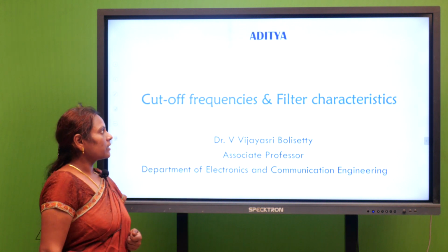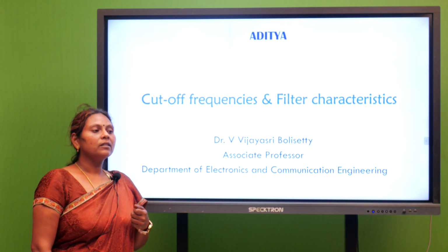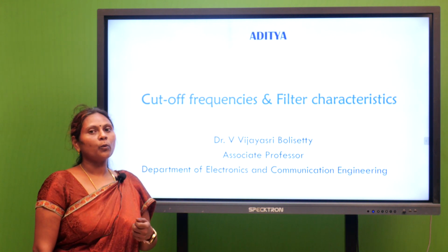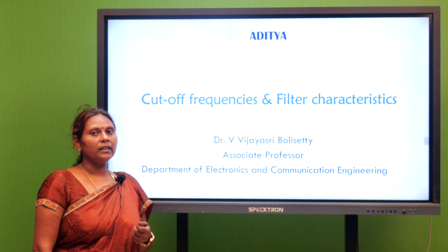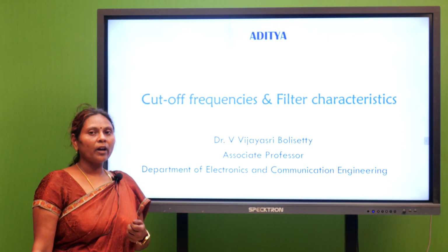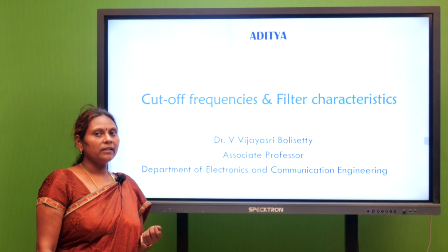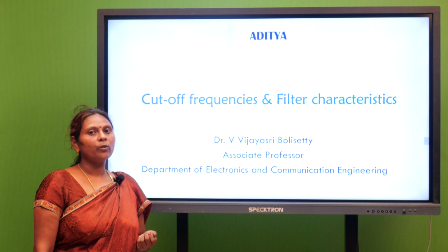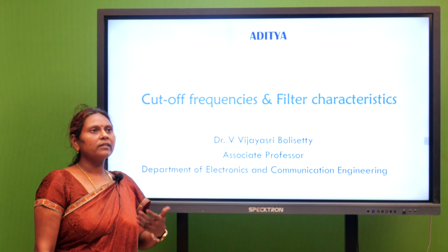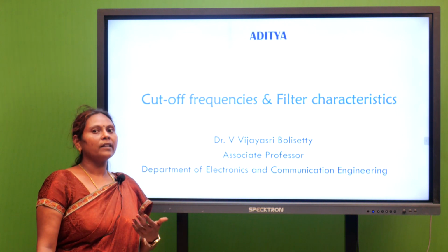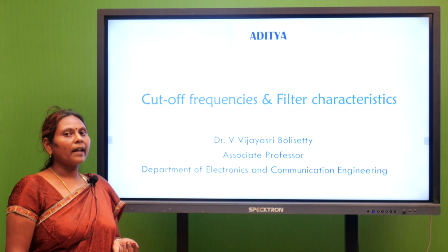So, what is a cutoff frequency? In the waveguides, we have seen that some of the signals are allowed to propagate through the waveguides in TE modes, and some of the modes are not propagating in the rectangular waveguides. For example, if you have seen TE and TM wave equations, for m equal to 0 and n equal to 0, either TE wave or TM wave does not propagate through the rectangular waveguide. And all the remaining higher order modes, for example TE modes with m and n having different values like zeros and ones, are propagating through the rectangular waveguides.